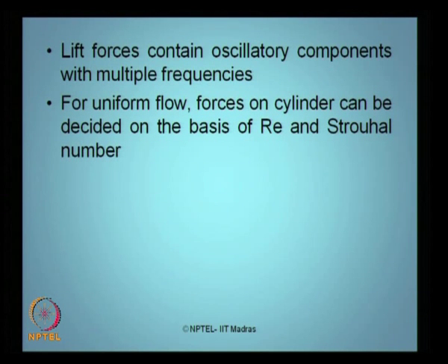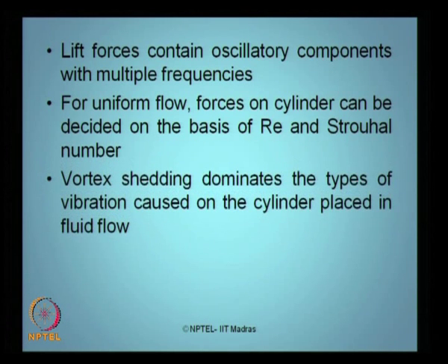So for uniform flow, forces are essentially governed by the Reynolds number and to some extent by the Stokes number as well, because we will talk about at what frequency the drag component will appear depending upon the Stokes number. Vortex shedding dominates the type of vibration caused by a cylinder in a fluid flow, of course if it is activated, depending upon the reduced velocity. If the reduced velocity is in a range of 1, 2 and 3, as we discussed in the last lecture, then the type of vibration imposed on the cylinder varies.